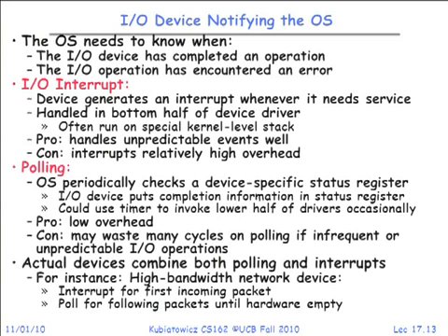Well, what actually happens is it's sort of a level triggered thing, so it turns the interrupt on, and then it's up to the software to turn it off again. So it just keeps returning the same bit on.